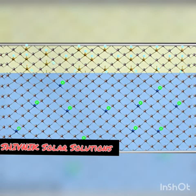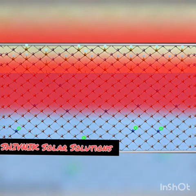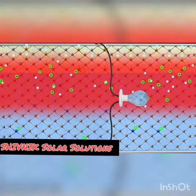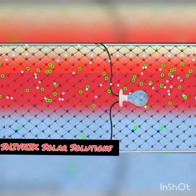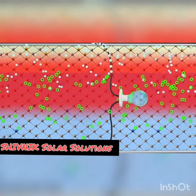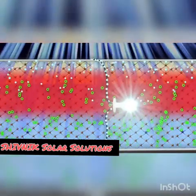Just observe the depletion region formation here. You should note that the thickness of the depletion region is much higher here compared to the previous case. This means that, due to the light striking, the electron-hole pairs are generated in a wider area compared to the previous case. This results in more current generation by the PV cell. The other advantage is that due to the thin top layer, more light energy can reach the depletion region.